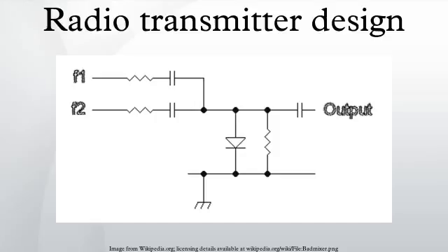Vestigial sideband modulation. Vestigial sideband modulation is a type of modulation system commonly used in analog TV systems. It is normal AM which has been passed through a filter which reduces one of the sidebands. Typically, components of the lower sideband more than 0.75 MHz or 1.25 MHz below the carrier will be heavily attenuated.